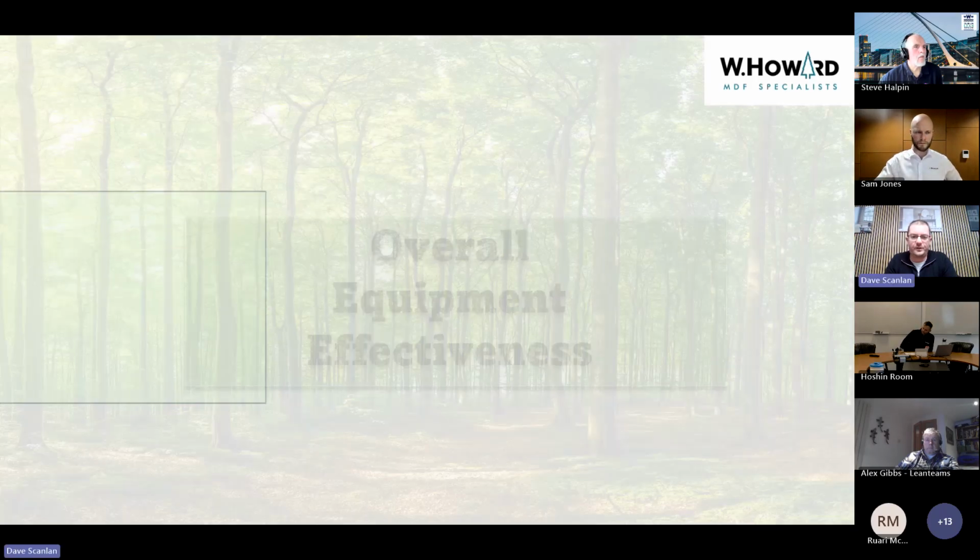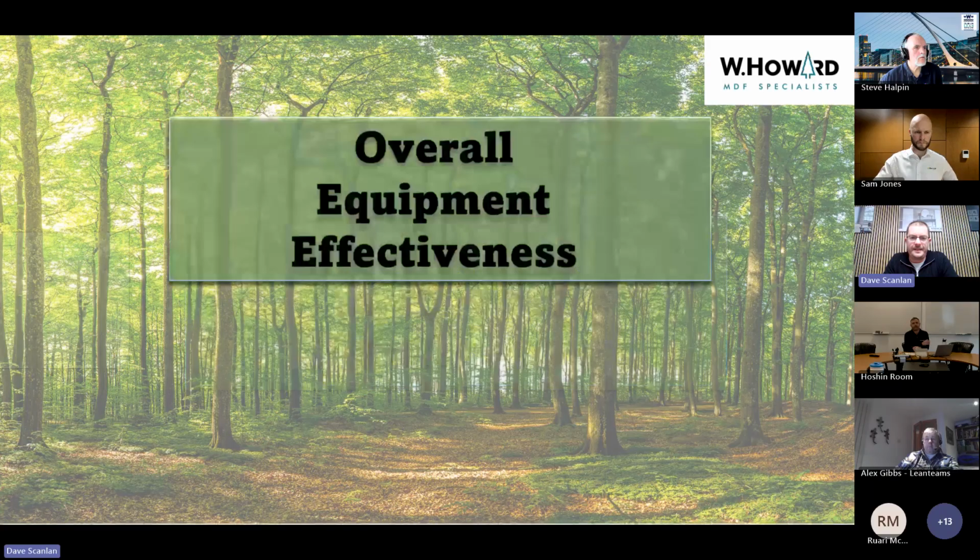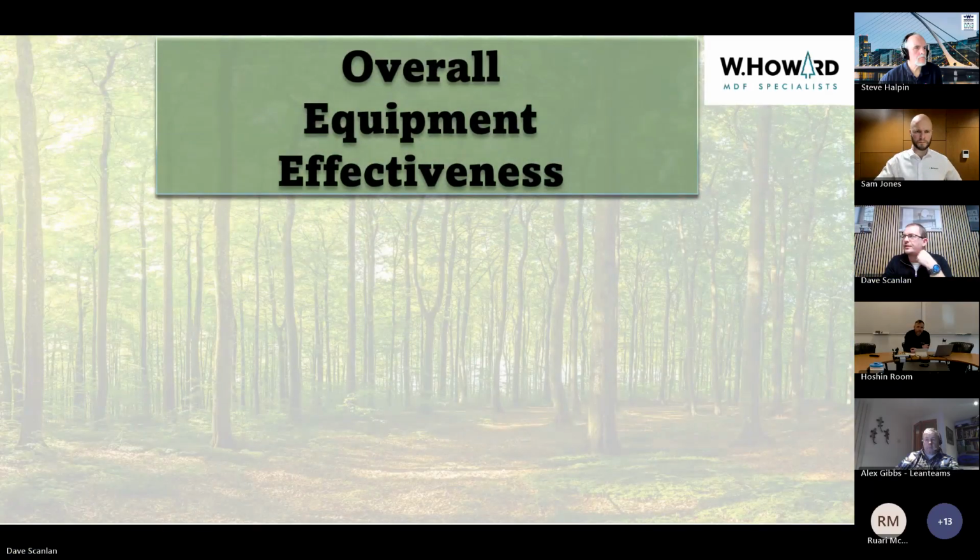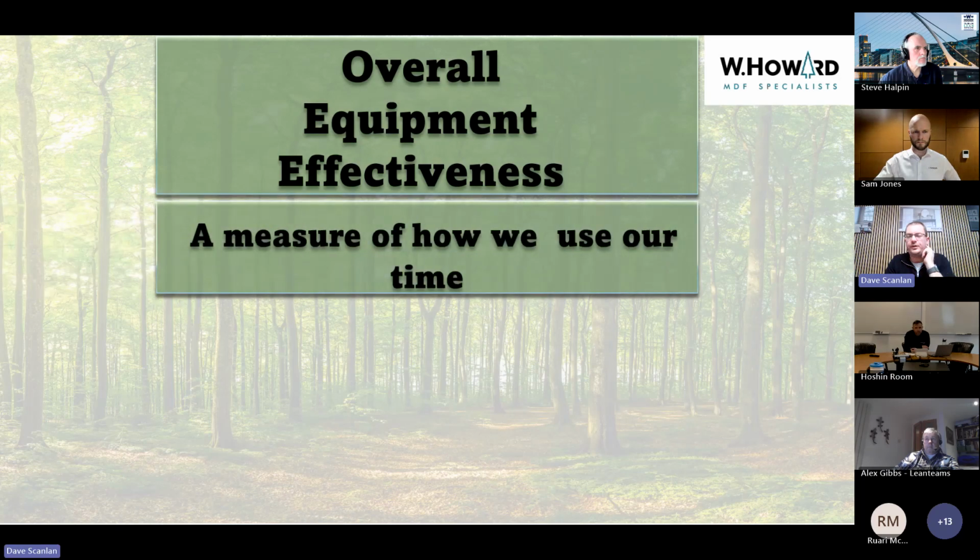Okay, so overall equipment effectiveness. There's a couple of things in it. There are 3 measures that we take. Our first measure is how we use our time. So as Sam was saying, availability, performance and quality.